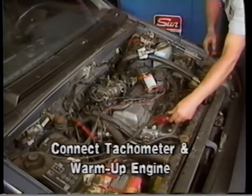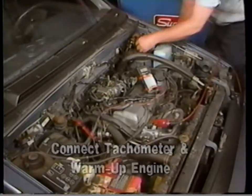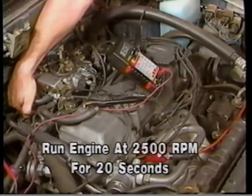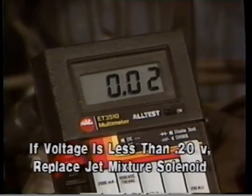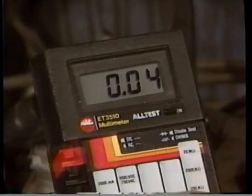Next, connect a tachometer to the engine and warm the engine to normal operating temperature. Run the engine at 2,500 RPMs in neutral for 20 seconds and record the maximum oxygen sensor voltage. You should note that the oxygen sensor voltage will vary continuously. Note only the highest voltage observed. If the maximum voltage is less than 0.2 of a volt, replace the jet mixture solenoid valve.